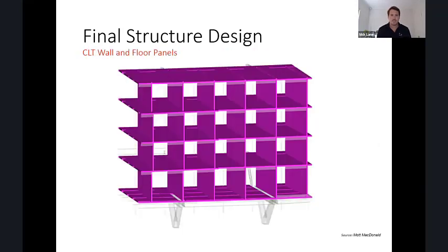So with regards to the CLT wall and floor panels, you can see that they're used to frame up the primary structural walls that are aligned with the V columns. They're also the internal walls between rooms, which we also used structurally as a vertical load-bearing system. The CLT panels would span across the walls, so there was some continuity there as well. But we obviously worked with XLAM and their design engineers, Vistec, to make sure that the structural system was transferring load onto the primary steel level 2 structure, as we designed it for. Next slide, thanks.